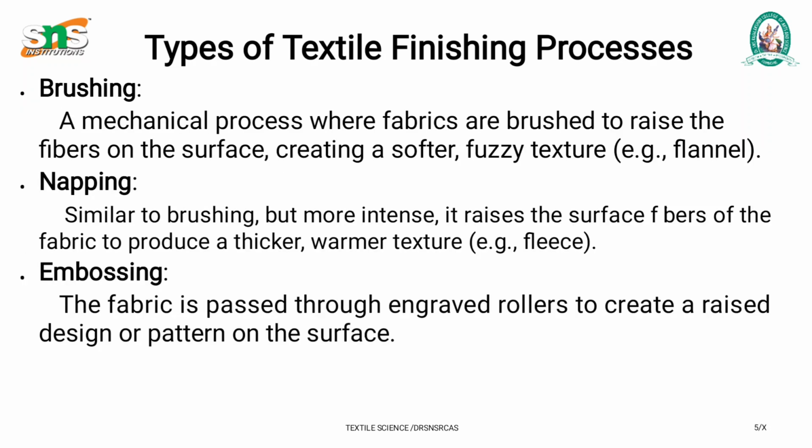Next, brushing. A mechanical process where fabrics are brushed to raise the fibers on the surface, creating a softer, fuzzy texture. Next, napping. Similar to brushing but more intense, it raises the surface fibers of a fabric to produce a thicker, warmer texture. Next, embossing. The fabric is passed through engraved rollers to create a raised design or pattern on the surface.